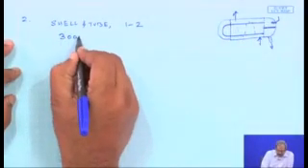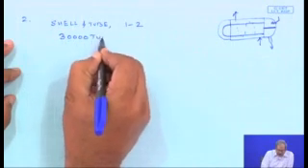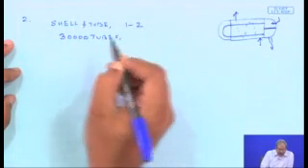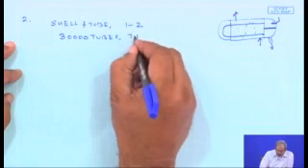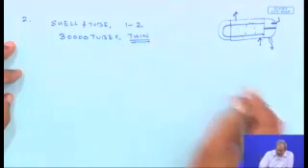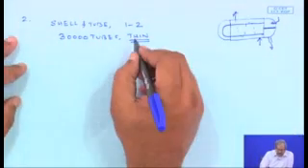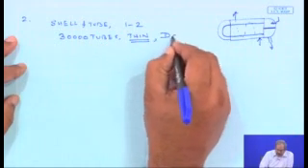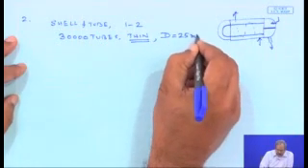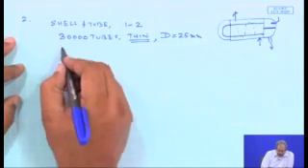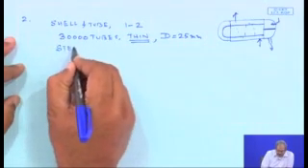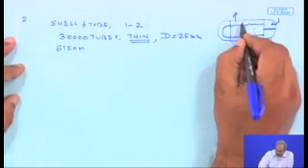There are 30,000 tubes, and the wall is thin, and since the wall is thin, the conduction resistance can be neglected. The diameter of each tube is 25 millimeter. The steam is condensing on the outside of the tube.